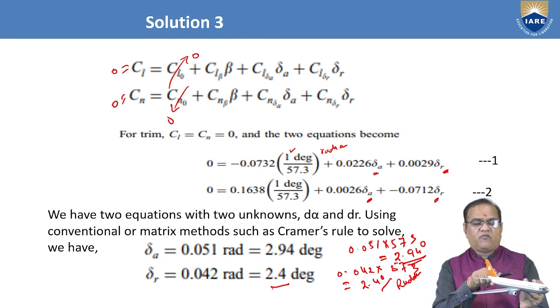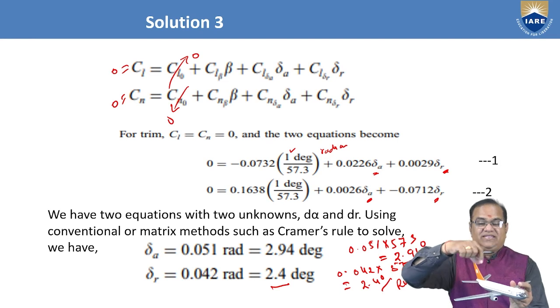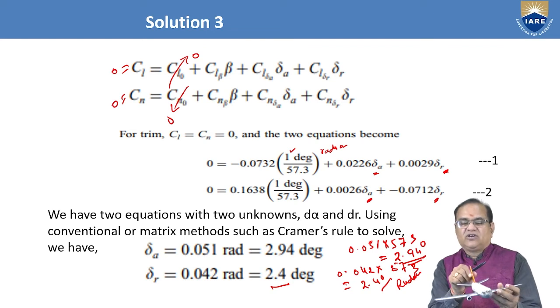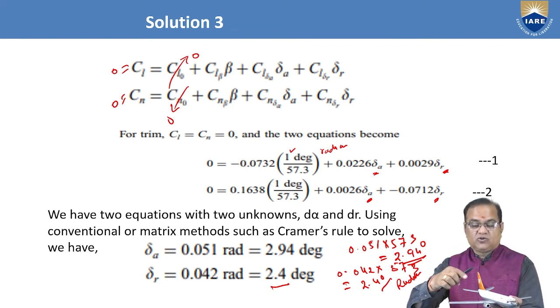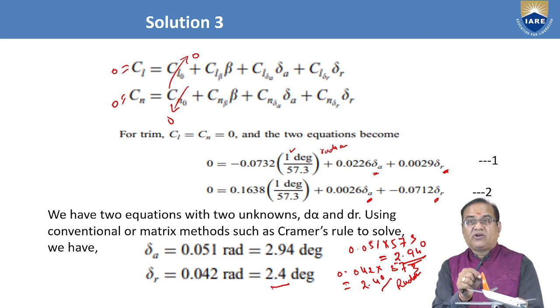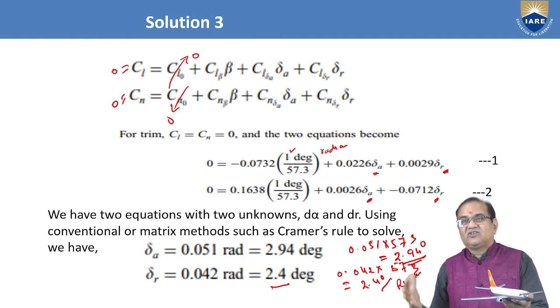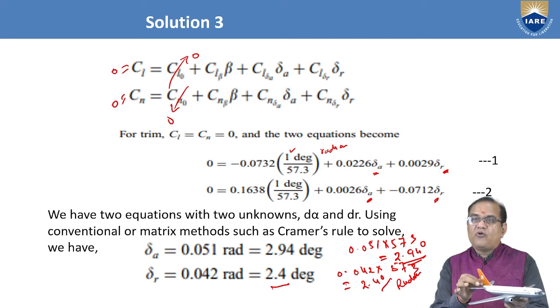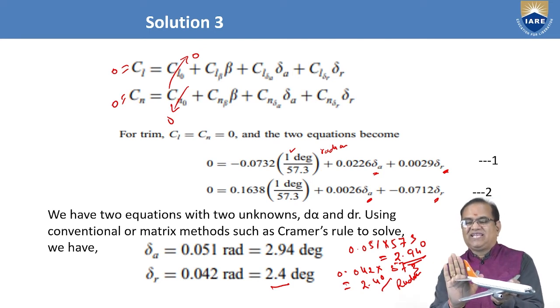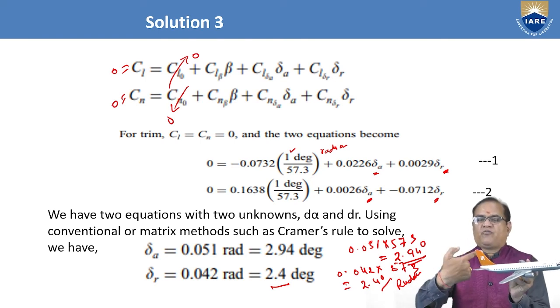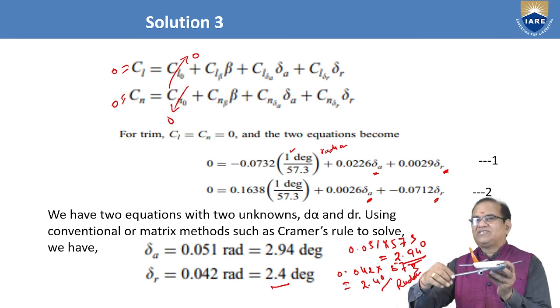If the force is generated here in this direction, the minus direction, it will go like this. So how will this force go? We have to make the right side. If your rudder is moving towards the right side, your right wing will go back. So you have to deflect your rudder 2.4 degrees towards the right. Initially it is like this, you have to deflect like this. So force will be generated, and this wing will go towards the right.